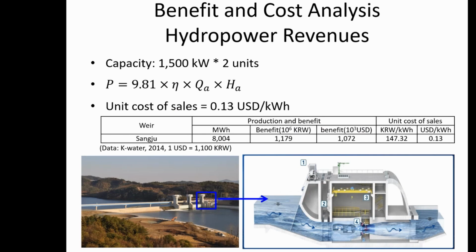So one of the issues for management has been that they want to use this micro powerhouse to generate some electricity. It's not huge. It's about 3 megawatts, 2 units at 1.5. So it's not generating a huge amount of power, but still, let's use it. What do you need to generate hydropower? You need a good head and some flow. The flow is limited to the turbine, so that is fixed, but the head can vary a little bit. So the benefits from using this powerhouse have been increasing with the stage you get upstream of the low head dam, as you can see.